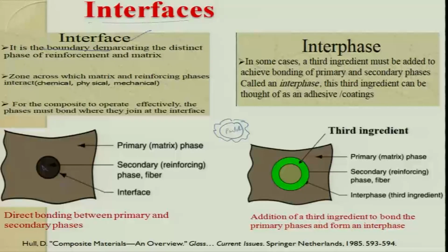And how do you enhance the interface? I will understand what material A is properly, I will understand material B properly, and then I will try to do some gelation in between A and B. That means I will try to functionalize A such that it makes a proper interface with B. So now there is in between a coating. In glass fiber I said silane coating; in metal matrix composite, when I said agglomeration has to be avoided, we try to functionalize the particulate. All these things are done to make sure you get a proper interface.